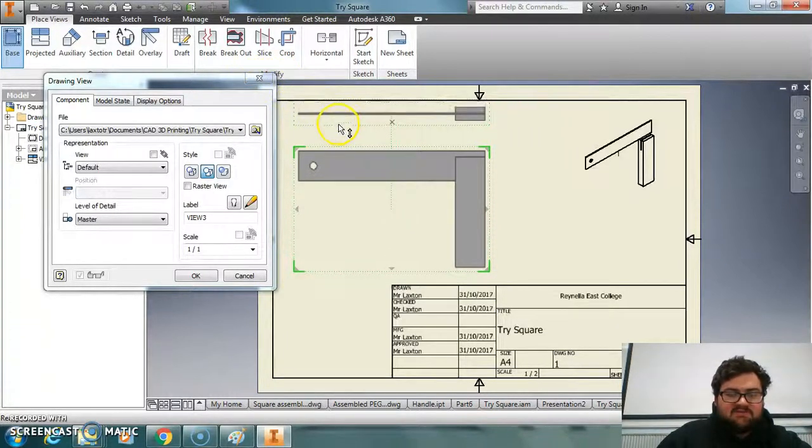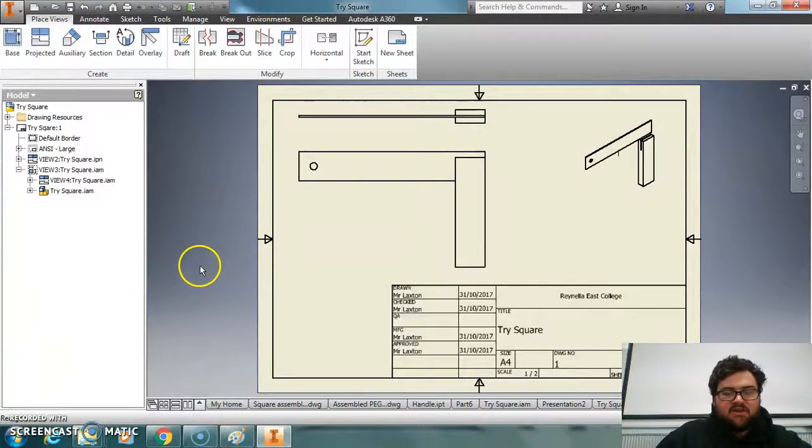and so you get the same sense that you can actually line up and you know all the lengths are the same. So I wouldn't put a dimension down for the full length of that and then put another one there, because you can see they're exactly the same. Okay, so you can see that's put in nicely.